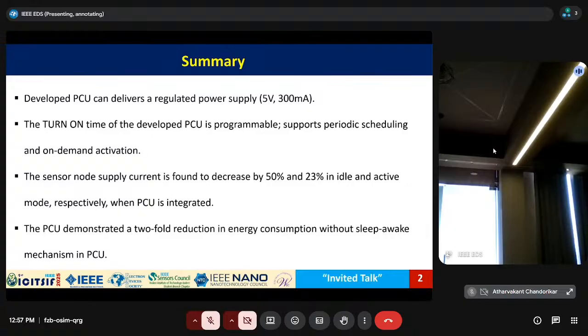Now at this increment I have not applied any kind of software optimization on the ATtiny microcontroller. If we optimize the ATtiny microcontroller further, using low power modes, reducing the clock supply, and putting it in deep sleep mode for the periodic data collections and waking up with the help of the watchdog timers which run internally in the microcontroller, then this 50 milliampere can reduce to 5 milliampere.